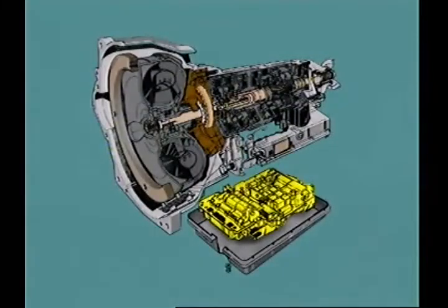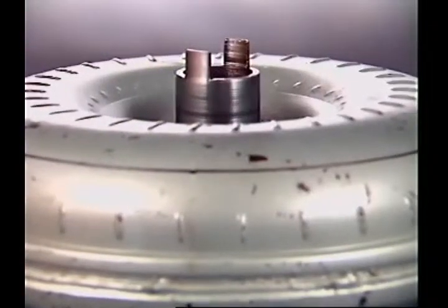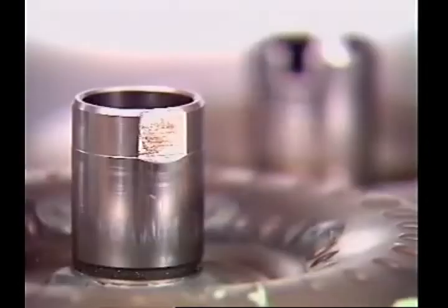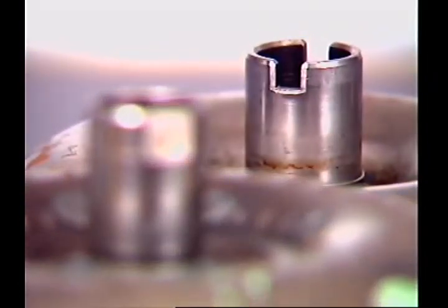The hydraulic control system requires a continuous supply of fluid under pressure, normally provided by a fixed displacement pump. It is driven by the torque converter when the engine is running. The pump driving member is engaged by tangs on the converter spout, or machined flats, or by slots.